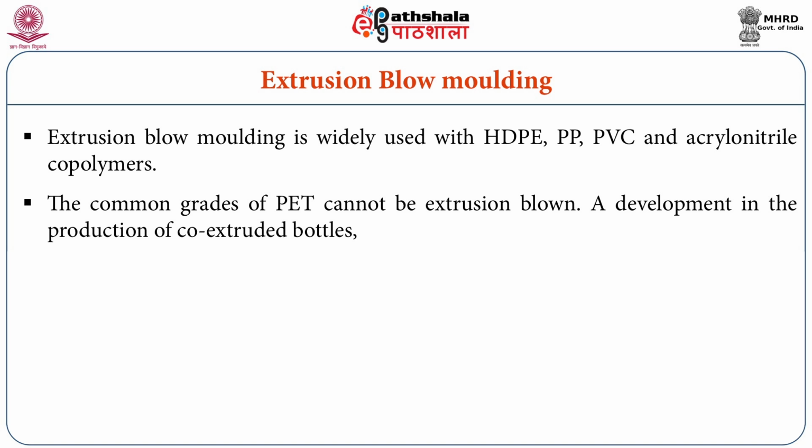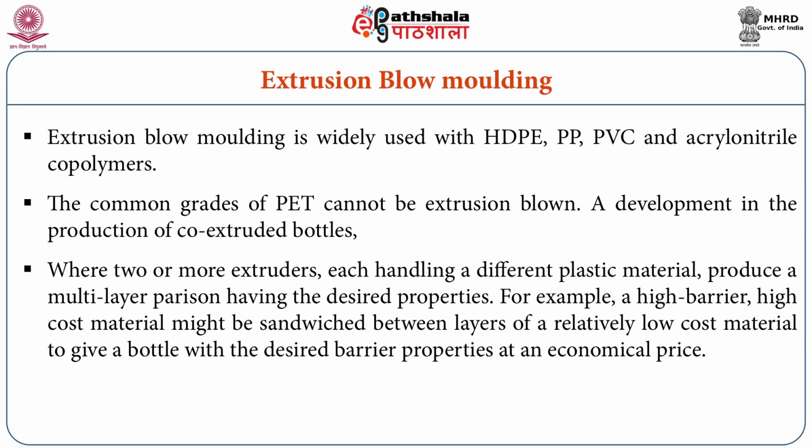A development is the production of co-extruded bottles, where two or more extruders, each handling a different plastic material, produce a multi-layer parison having the desired properties. For example, a high barrier, high cost material might be sandwiched between layers of relatively low cost material to give a bottle with the desired barrier properties at an economical price.